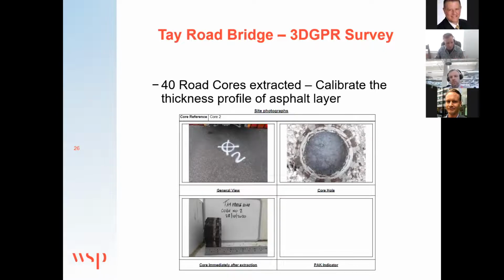Step frequency has a lot of advantages here because you can resolve very fine details near the surface, but also keep the resolution as you increase in depth. So small object detection, and you retain that resolution as you slowly move into more of a depth volume. Where the lower frequencies start to come in, you retain that resolution. So it gives you a good optimized system.